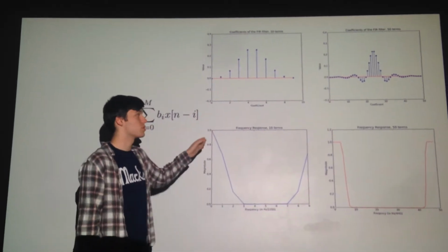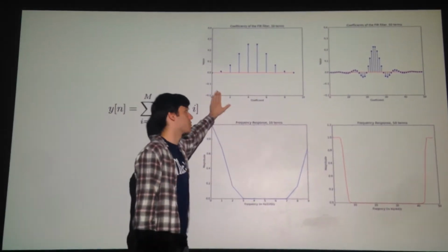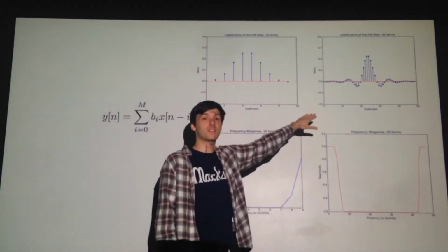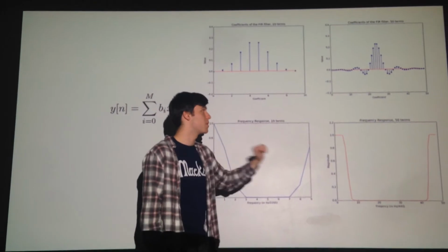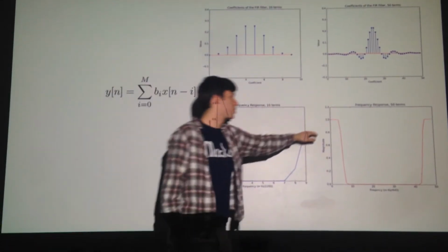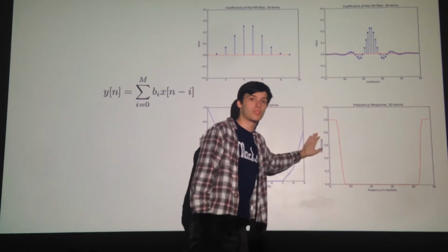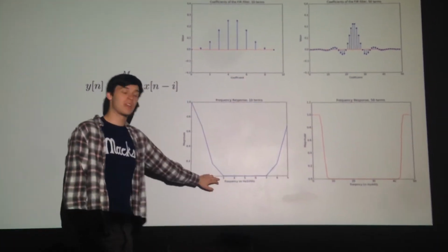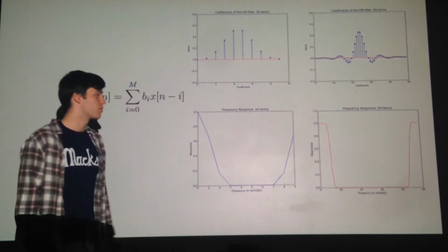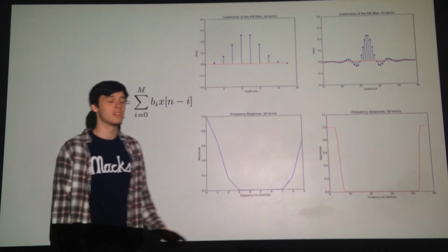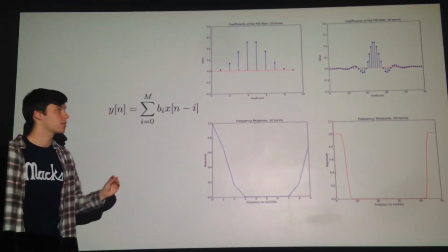We used two filters to try different things. The first filter only has 10 terms, and the second one has 50 terms. As one would expect, the 50-term filter actually turned out to be a much better low-pass filter, because you can see in the frequency domain there's the sharp cutoff after allowing some low frequencies through, and the high frequencies are fully cut off. With 10 terms, there's a sloped one, which is not fortunate. There's a high frequency component as well, because the FFT is symmetric.